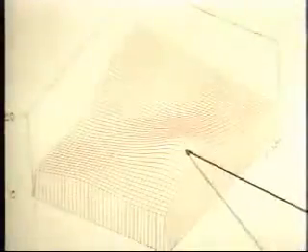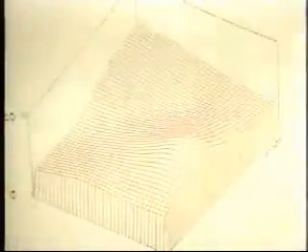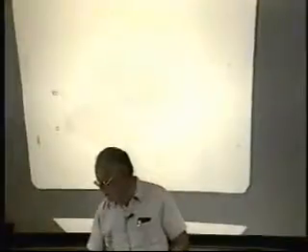So actually, two of the wells here, we figured that we'd fracked down into the Winfield when we were doing the stimulation of the Kreider. And when we did that, everything kind of fell into place. So even though it wasn't actually physically perforated there, once we did that, everything lined out.